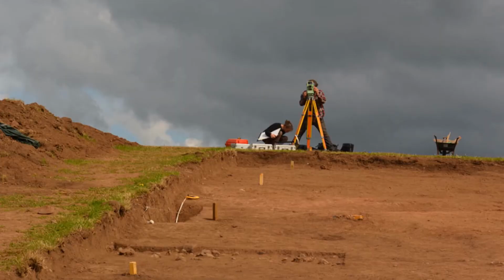On most commercial sites now, there will be no physical grid, and you will have the coordinates for your planning located with either a diff GPS system or a total station. But if you understand the concept of local grids and how they work within national coordinate systems, then you'll never be lost on site again.